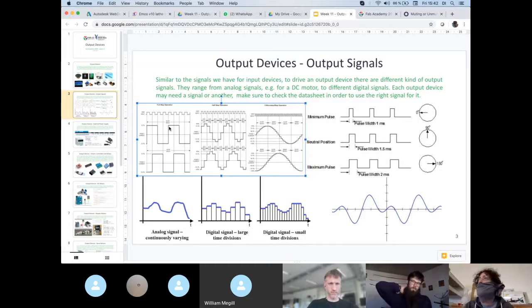Usually in many 3D printers, and also in the machine that I'm making here at home, the microstepping resolution that I'm using is 1/16. This means that we can make 200 times 16 steps, so 3,200 steps per rotation. Combined with the different kinds of gears, pulleys or whatever you use to move your system, it results in a different resolution of your system. So this is the way that you drive the stepper motors.